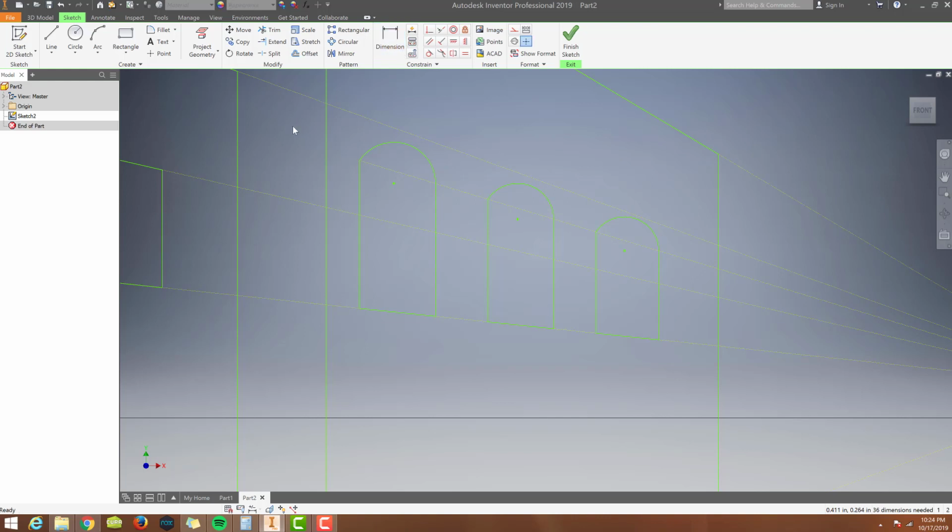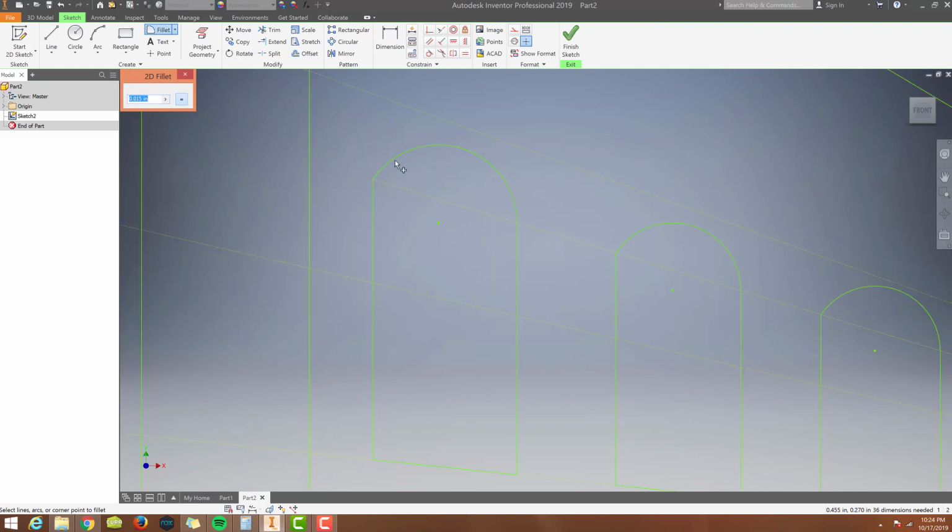And I'm going to then use the fillet, and in the box over here, I'm going to essentially do that number, but I'm going to divide it by 10. So since mine was 0.15, mine is actually going to be 0.015 fillet to start, okay? Because that's the measurement I got there. When I measured this line, I got 0.149, and I rounded it to 0.15. So I'm just going to make it 0.015. That 0 is very important.